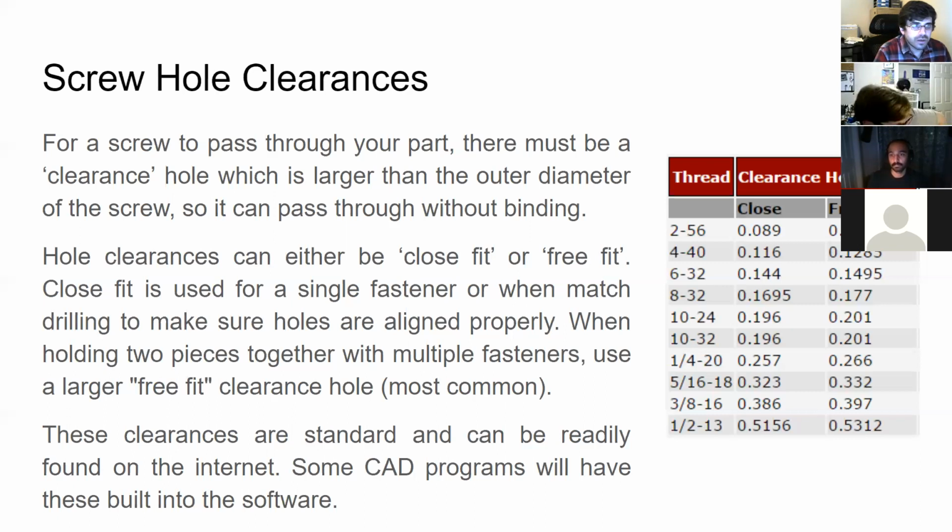Yeah, so a very common technique when you're assembling something that has multiple screws is to get all the screws in before you tighten one of them, because it just needs to have those screws there to kind of align. In the industrial world, using a screw to align something is very frowned upon. There are much better ways of aligning parts together than screws, which we tend not to use in FRC, but they definitely exist. Screws are for clamping, not for aligning.